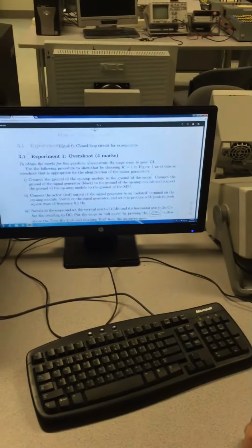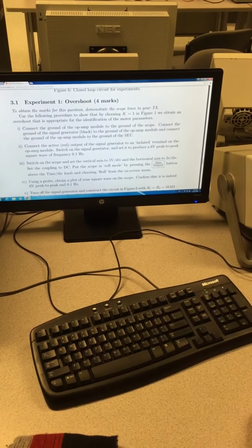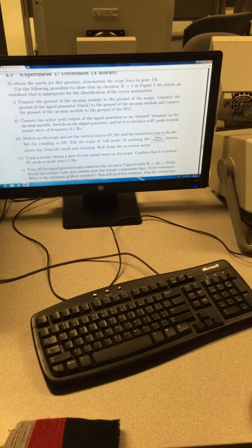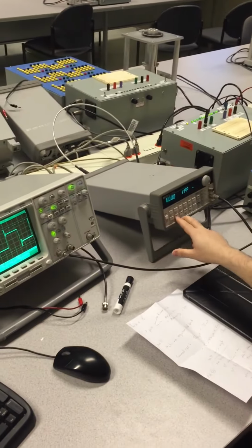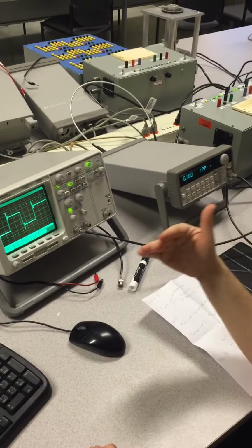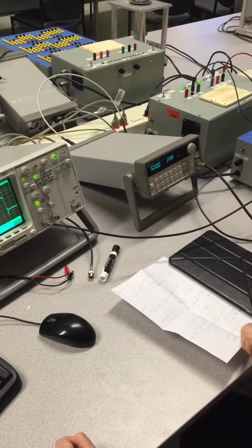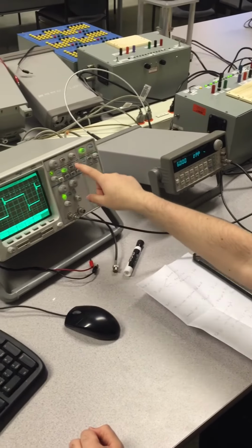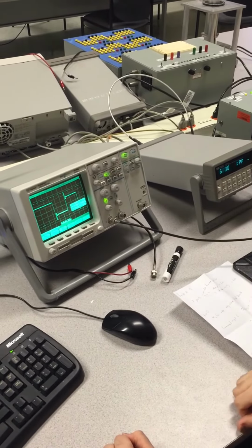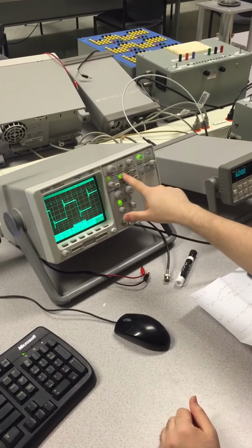In the PDF, it will ask you to adjust some parameters in the oscilloscope and function generator. Simply, first of all, we'll have a frequency of 100 millihertz, amplitude of 6 volt peak to peak. It is a square wave. So we will require that the volt become positive 3 volt, then negative 3 volt, positive 3, negative 3 alternatively. For the oscilloscope, we'll press main delayed and choose the roll mode for the display so that the display is continuous. You can open the quick measure so that you can get the peak-to-peak amplitude.